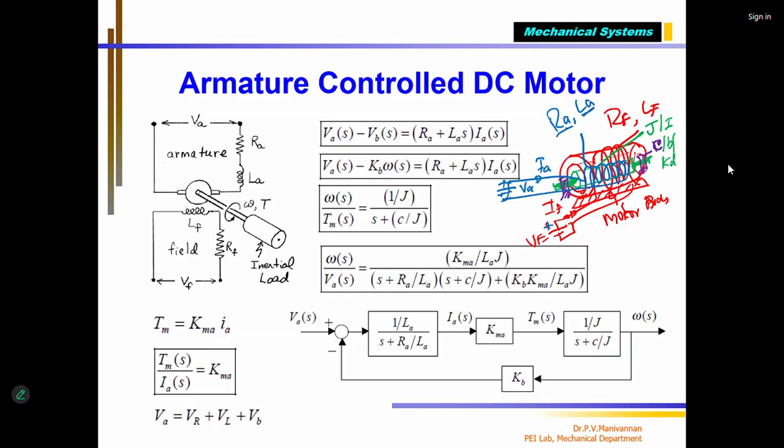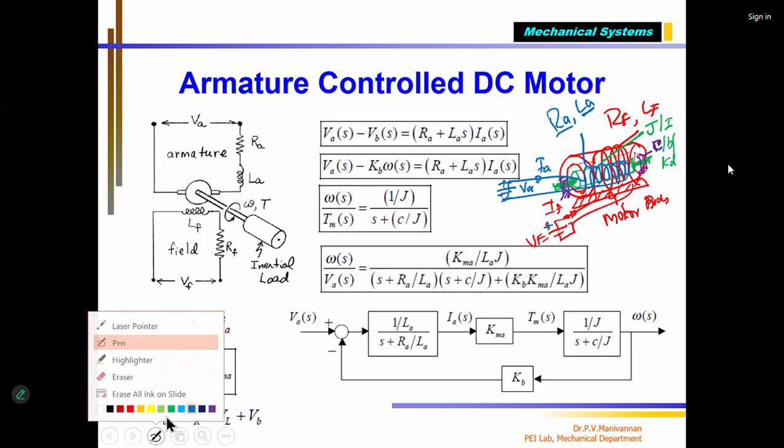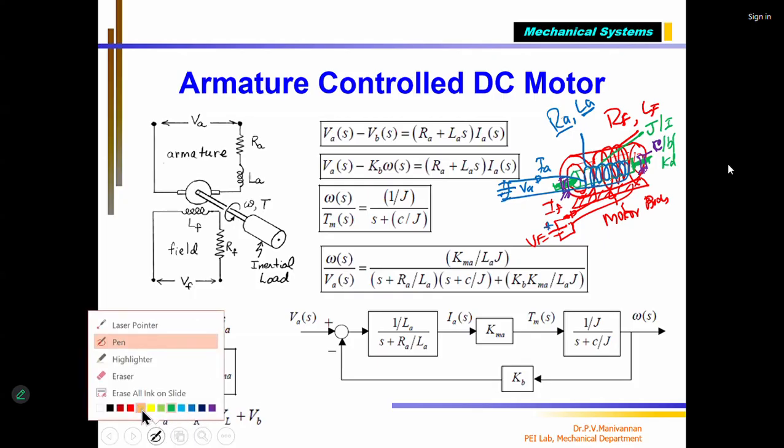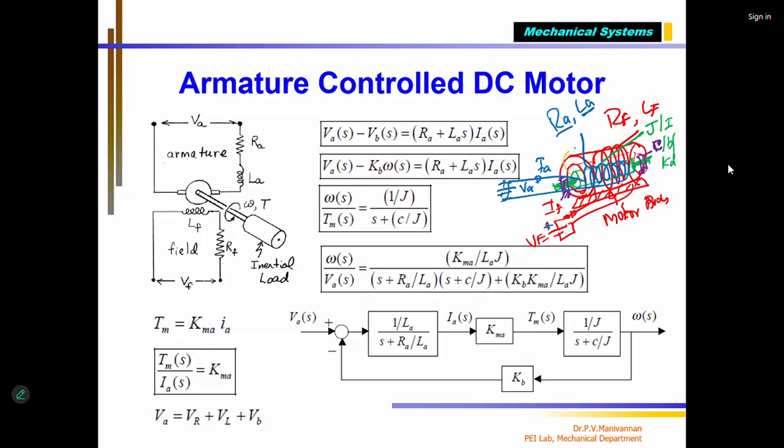Now, since the armature is rotating, once you apply the current to the field coil, correct? We applied current to the field coil. The field coil produces magnetic flux. I'll show you the magnetic flux in this one. So it produces a magnetic flux, something like this, from the field coil which is on the body.